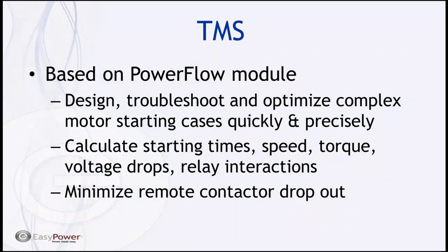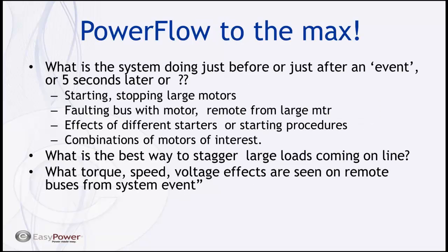Transient Motor Start is actually one of the more fun modules to work with. It's based on PowerFlow, and what it allows is the ability to design, optimize, and troubleshoot motor starting cases relatively quickly, be able to look at things like starting times, starting speeds, torque, voltage drops, and relay interactions, and also be able to ascertain if you're going to have a problem with contactor dropouts.